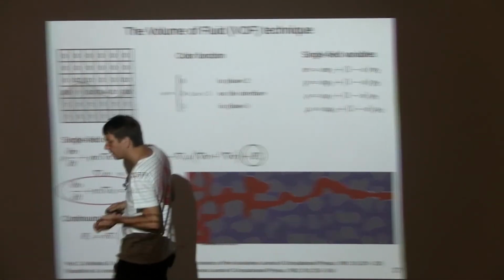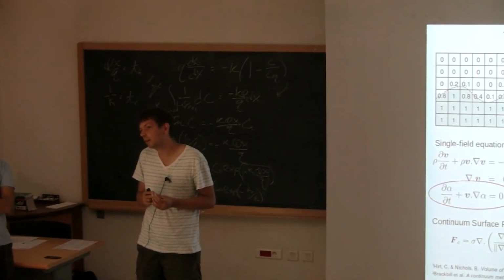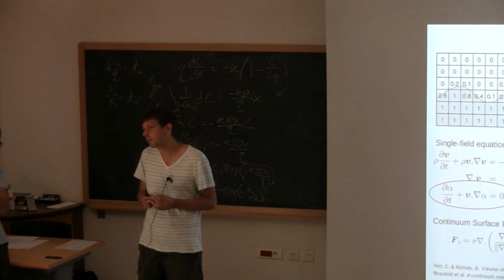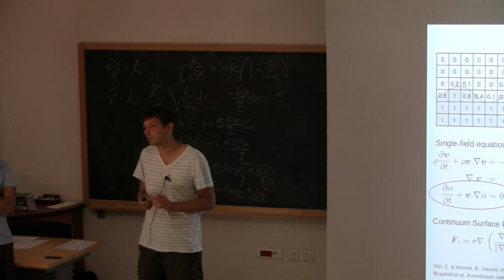In the Stokes flow solution, you have both the velocity field and the pressure, and then you suggest a first solution for the velocity, and from that you get the pressure. But at the first steps of the iteration process, you can say, okay, what you suggested as the velocity is incorrect, and then you need to try another guess for the velocity.